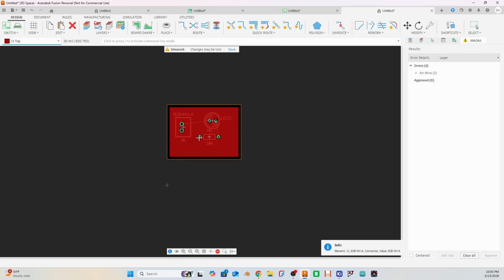What we want to do, you can see that there's a little net that's gone. Those little tiny wires are called air wires. They just give you a little bit of visibility so you do the wiring right. So when we do the copper pour, you can see that those grounds are gone. There's no more wire between those two. Essentially, it's the ground, so everything is connected to the board, and that's a simple way to link all the grounds together.